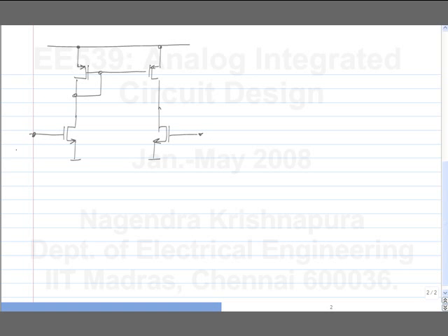So this is at some V bias. Actually, the first part of the circuit asks you to calculate the swing limits, right? You can think of this as a transconductor and it's terminated in some voltage source. So what's the maximum and minimum values of V out?